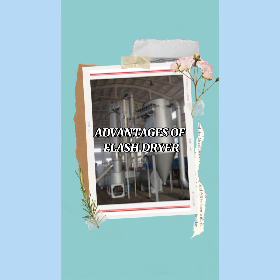Advantages of flash dryer. Firstly, short contact time and parallel flow make it possible to dry thermolabile material. The thermal contact between the conveying air and the particle is usually relatively brief. Therefore, flash dryers are best suited to removing exterior moisture, which is surface moisture rather than interior moisture.